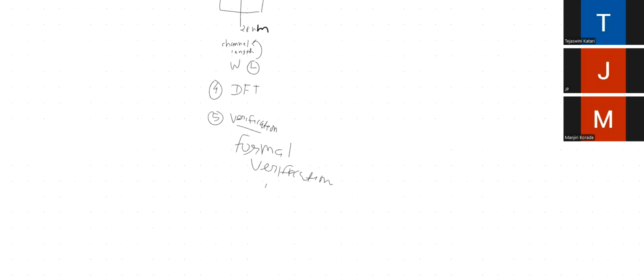Okay, so the answer is here only. After RTL, we are doing some process and then only we are getting the netlist, right? So during that process, that is nothing but synthesis or DFT, it is possible that your functionality might change. So by mistake, instead of an OR gate, an AND gate is added. It will change the whole functionality. So that's why we need to do formal verification.